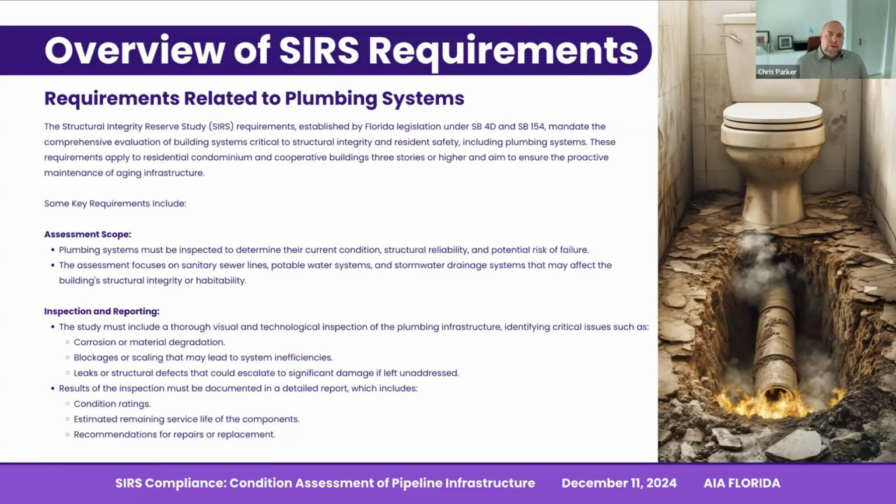What a lot of places are doing, if it is specified that you need to reinstall cast iron, the recommendation from us and within the industry in general is to do what is called a pre-coated or pre-epoxied piece of cast iron pipe, where the internal lining of that pipe has already been covered or impregnated with an epoxy resin that immediately increases the life.